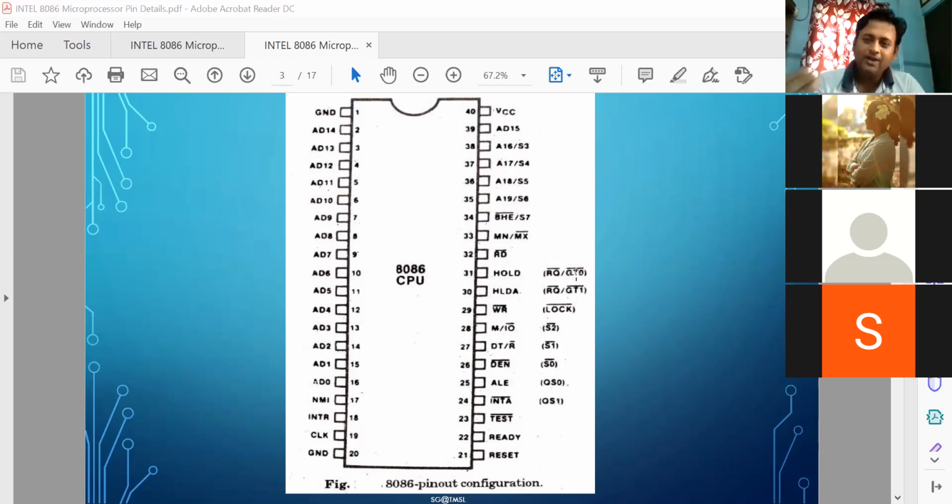Execution is performed as long as the queue is not empty. When the queue has been filled up by the fetching operation, no fetching is performed until the upper 2 byte space is empty, but your execution continues going on. The fetch gets stopped, but not the execution.